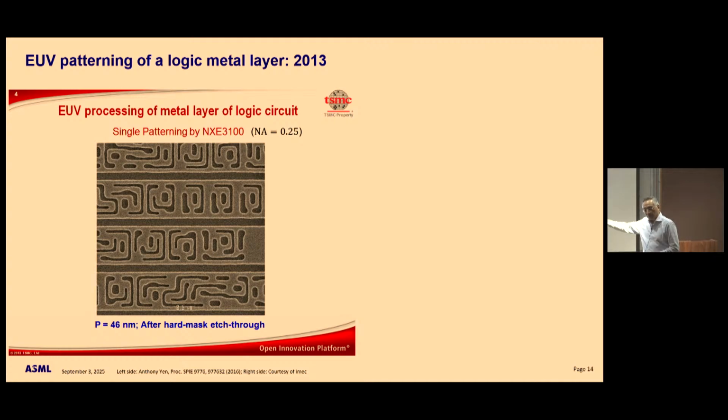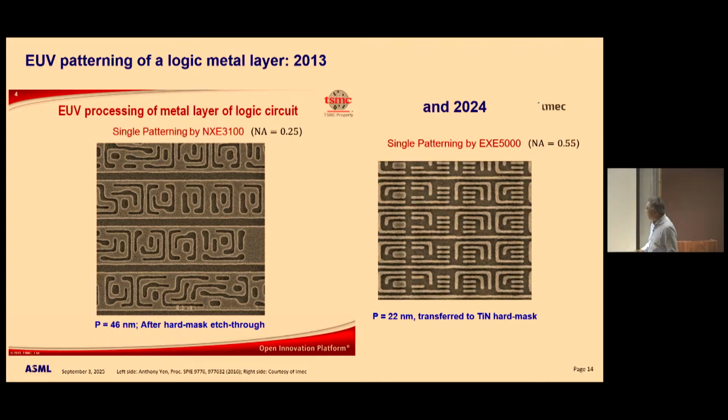In the end, the 10 nanometer was a 1D design because EUV could not make it, and then TSMC had to continue with immersion lithography, right? So we changed it to a self-aligned litho-etch process and a 1D design. But had EUV been ready, we would have continued with the 2D design. Okay, that's another story. Now I want to just give you a sneak preview.